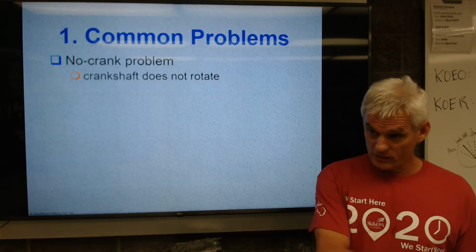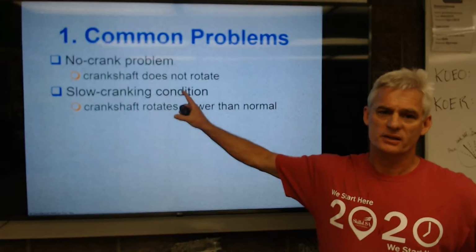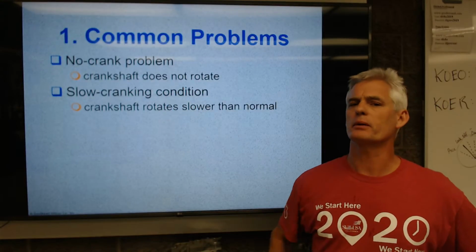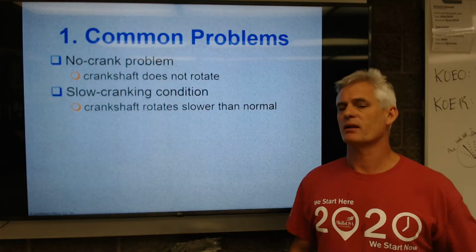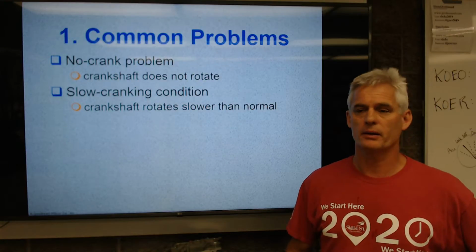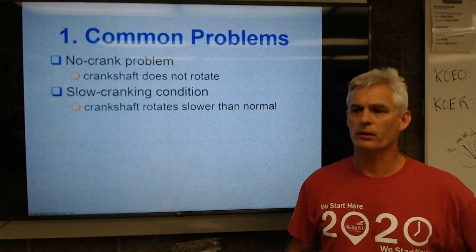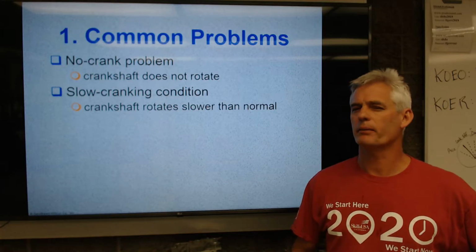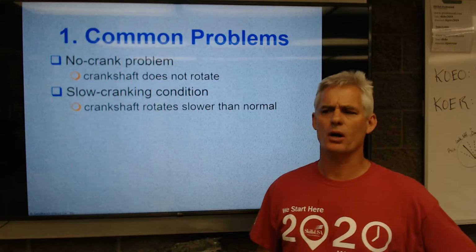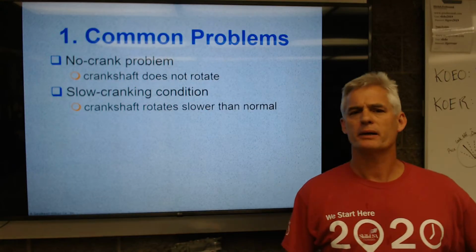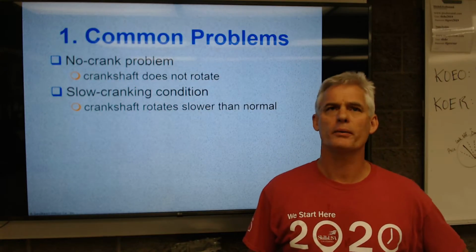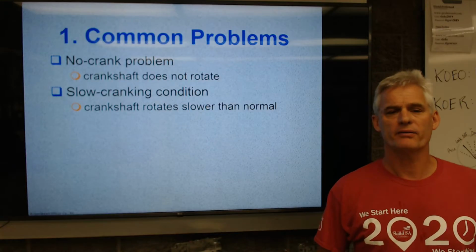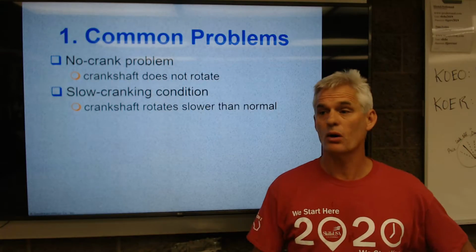Secondly, when we have a slow cranking condition, typically we're thinking we have a battery with a low state of charge. Obviously, the theft system is not compromised because it wouldn't crank at all. So if it's cranking at all, we're thinking, okay, either I have a battery with a low state of charge, or maybe I've got bad connections to the battery, or is it possible that I have high mechanical load in the engine because something's wrong in the engine?